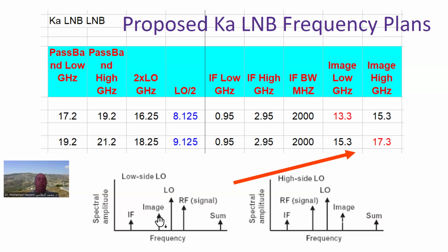So what that means is the lower side frequencies of this image will be the higher side and vice versa. That's why a lot of times, if the noise figure on your low noise block is deteriorating on the upper half versus the lower half, and you try to troubleshoot your image rejection filter, it's very confusing because of the fact that the image is translated inverted in frequency.